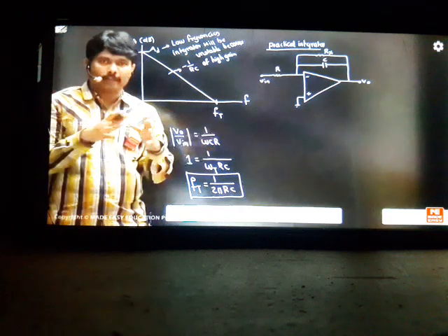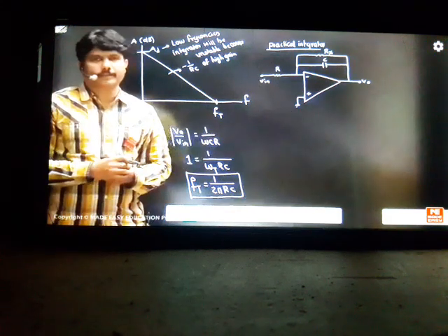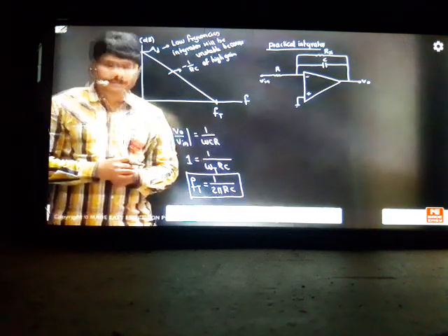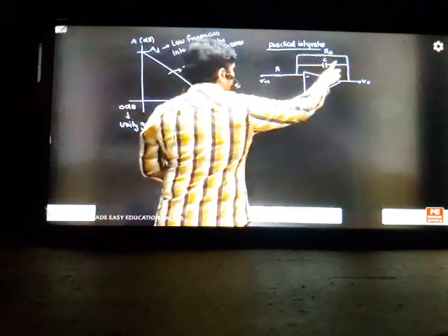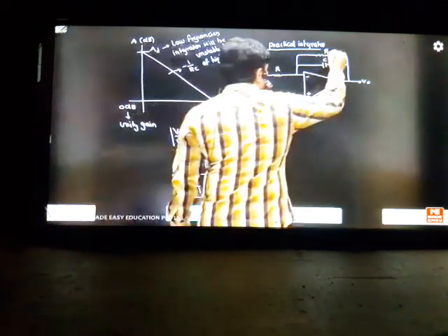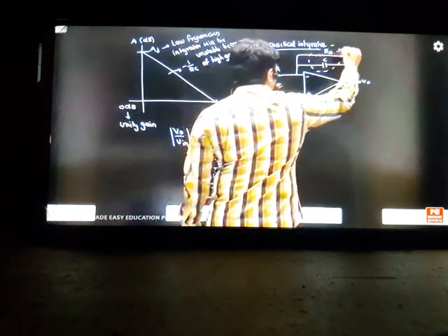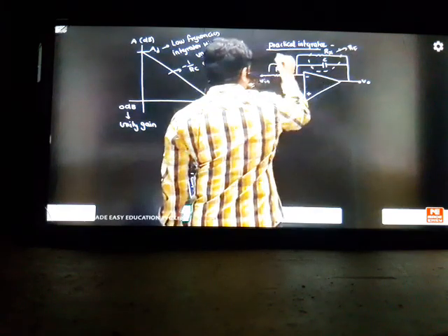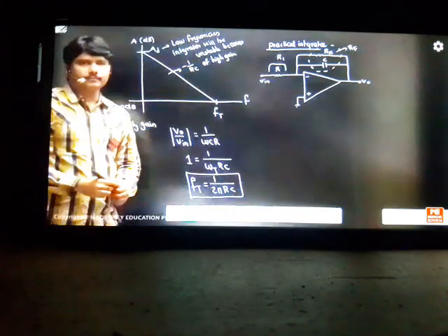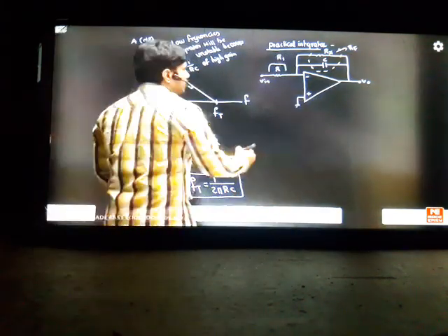When it opens, the op-amp is not working in closed loop, it goes to an open loop system, so it becomes unstable. So it has to be in closed loop. That is required. That's why I kept a resistor across the C. If you keep it like this, this total combination will become your RF in the circuit, and this will become your R1, so the transfer function will change naturally. How much is the transfer function? Let us see. So first, what is the RF simplification?